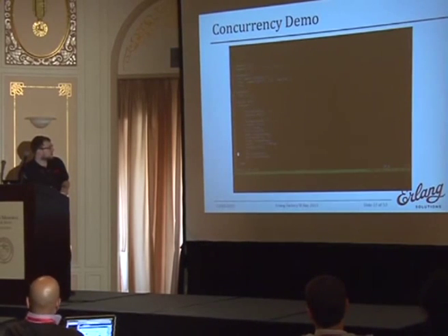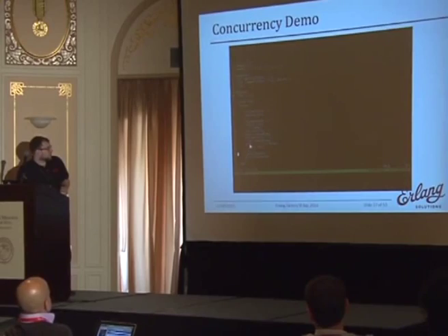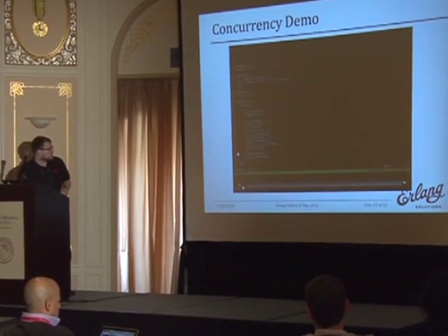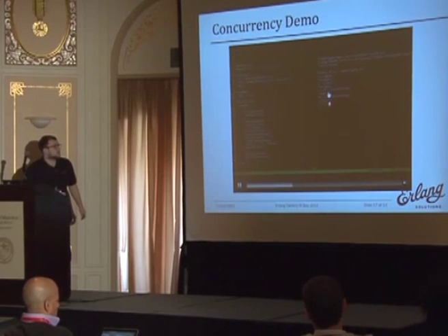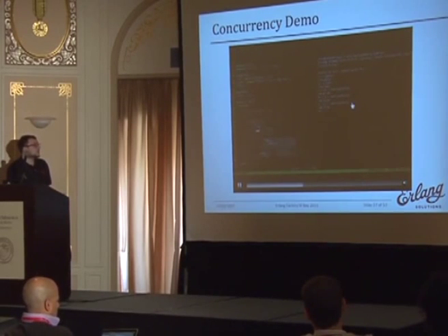I don't know how well you can see it, because I should have inverted the video, really. But just to show you that this works and it's kind of fun, I'm going to have 3 LEDs connected to 3 different pins. This is just a simple module that I have. I'm initializing it. The first one is connected to 18. If you can't read it, it says L0 equals LED start 18, 21, and 22.